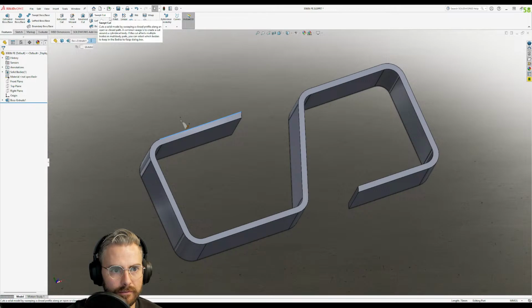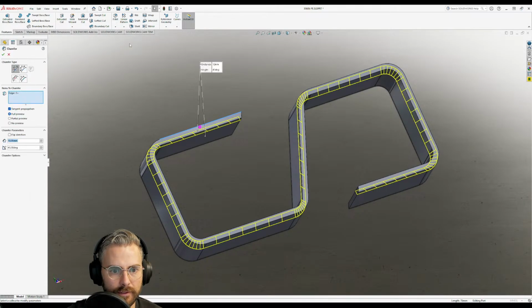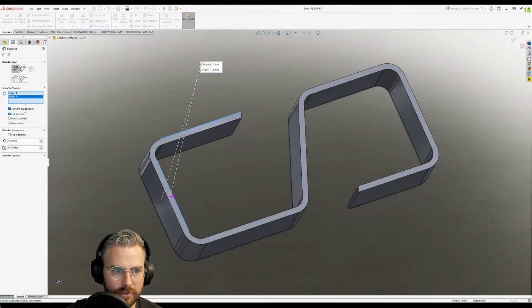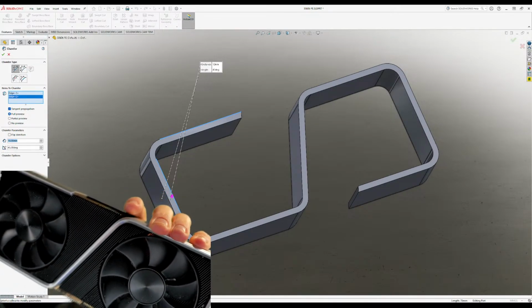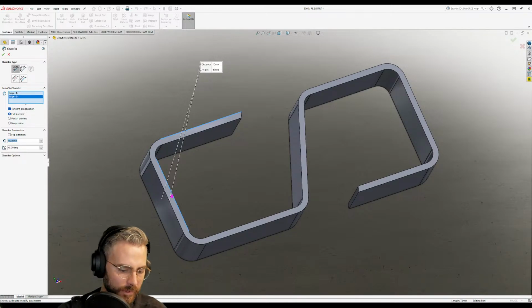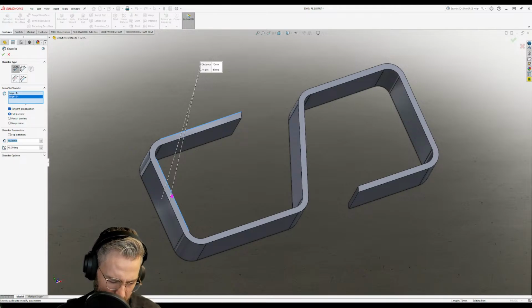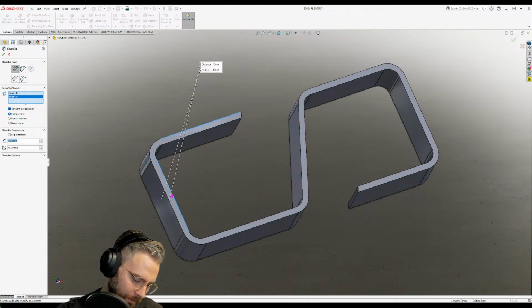So I'm going to quickly do a chamfer on this. This guy is chamfered. So you can break edges on here. So this is 10 mil chamfer. It is definitely not a 10 mil chamfer. This is 5 millimeters wide. There's a chamfer on either side. As you can see on these, there's like that facet on there. That's the chamfer. And it doesn't even go the full thing. I'm going to assume it's a 45 either way, which it kind of looks like. And it looks like it's even, symmetric.